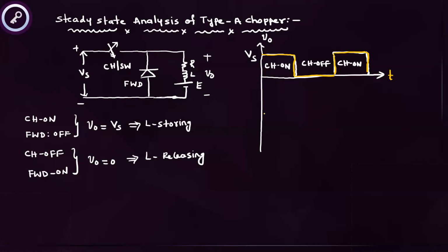Friends, if you draw the output current waveform, during the chopper on state the inductor is storing the energy, and the current is rising.